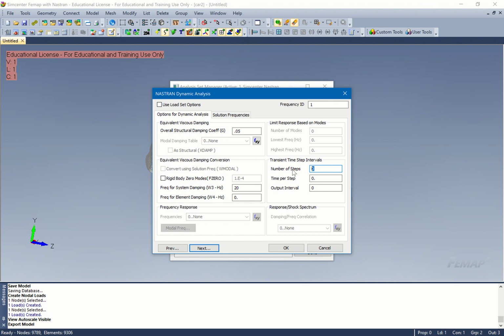So let's just see, because these are very, very limited resources. If we do it 1,000 per second for 2 seconds, let's just try this. Put in 2,000. Time step is 0.001 for stability. But let's put out every 5 steps. So that's going to give us 400 time steps. We'll see if that works. Because this is an internal step, but it only actually saves every 5. Does that make sense to everybody?